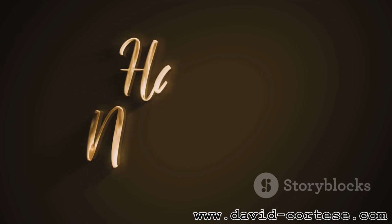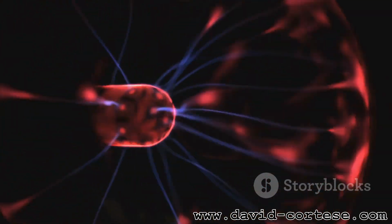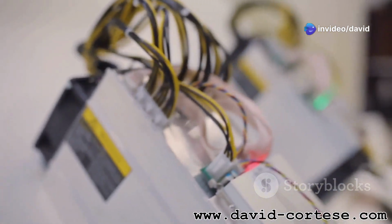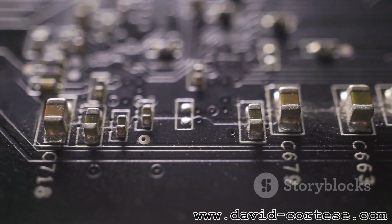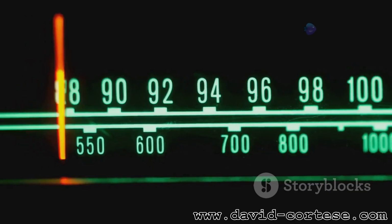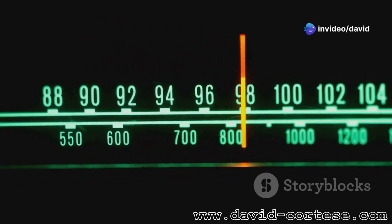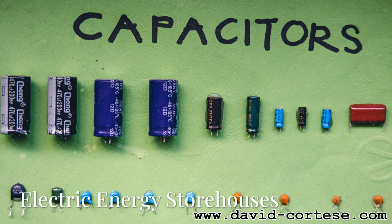The unit of inductance is the Henry, H. The higher the inductance, the stronger the inductor's opposition to changes in current. This property makes inductors invaluable in circuits where smoothing out current fluctuations is crucial, such as power supplies. Inductors are also used in filters, which selectively allow or block specific frequencies. By combining inductors with capacitors, engineers can create circuits that resonate at specific frequencies, forming the basis for radio tuning circuits.